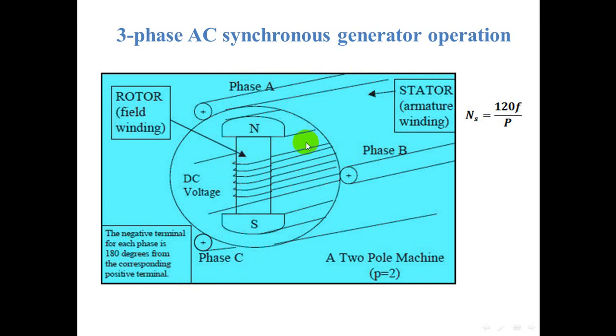If the turn is again rotated towards a vertical position, then the induced current reduces to 0. Thus, for one complete revolution of the rectangular turn, the current in the conductor reaches a maximum and reduces to 0, and then in the opposite direction it reaches the maximum and again reaches 0.